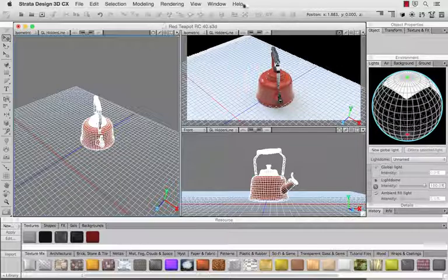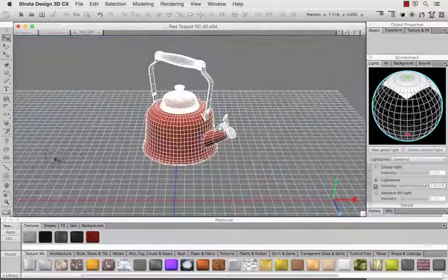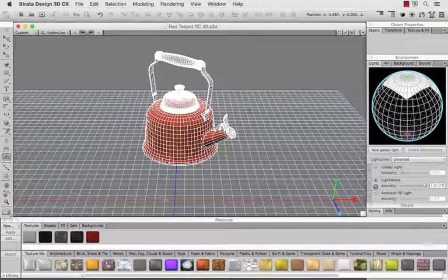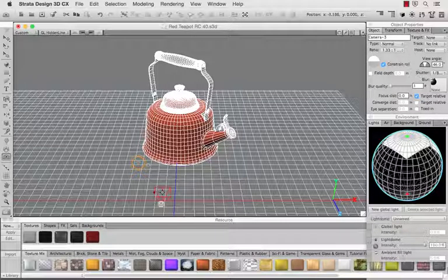Like other objects that you can draw into your scene, cameras are inserted using a tool from the tool palette. Cameras draw in just like the spotlights that we covered earlier in the lighting video. You can drop a camera onto the active grid with a single click, or you can click and drag to establish the initial view direction of the camera.